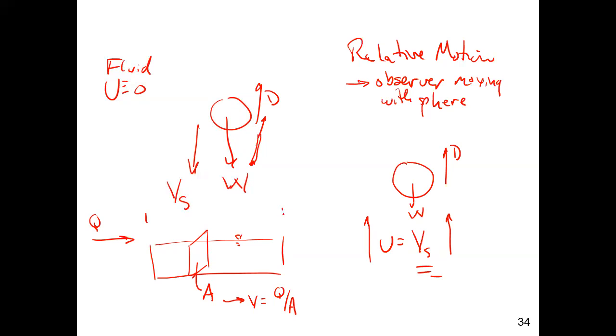And what we do is try to size the length and the depth of this basin such that when a certain particle size enters, it's being acted on by the settling velocity. And before the fluid hits the end of the tank, that particle settles out.